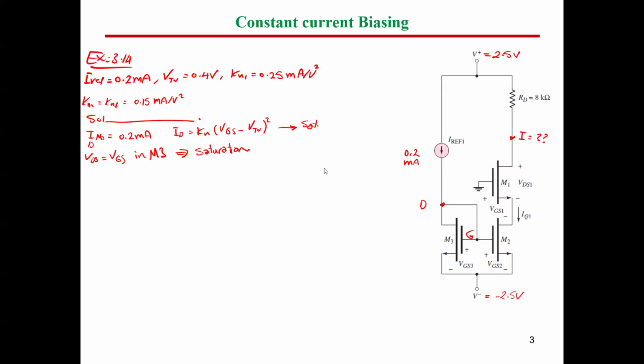Okay, so as we agreed again, guys, MOSFET number 3, since the gate and drain are shorted together, V drain to source equals VGS, and we drew the characteristic of this case in the previous class when we discussed the load and drive MOSFET operation. And we agreed that this type of connection will make the MOSFET work in the saturation region all of the time. So this is going to be now the equation of the third MOSFET M3.